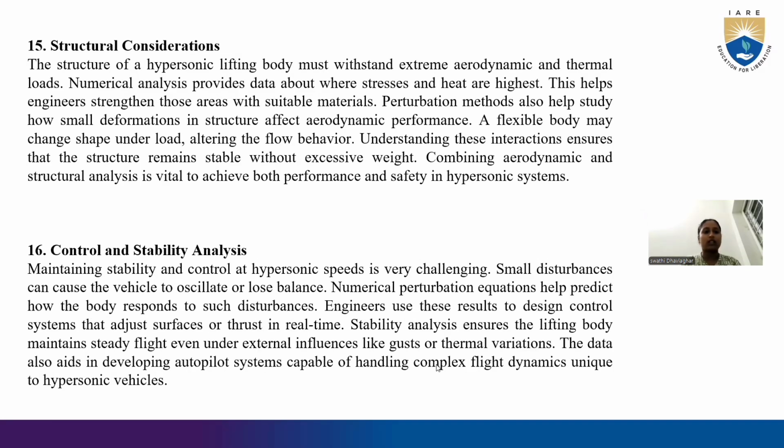Structural considerations. A hypersonic lifting body must withstand extreme aerodynamic and thermal loads. Numerical analysis provides data about where stresses and heat are highest. This helps engineers strengthen those areas with suitable material selection methods. It also helps study how small deformations in structure affect aerodynamic performance. A flexible body may change shape under load, altering the flow behavior. Understanding this interaction ensures that the structure remains strong without excessive weight. Combining aerodynamic and structural analysis is vital to achieve both performance and safety at hypersonic speeds.